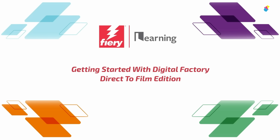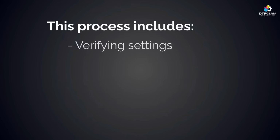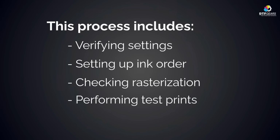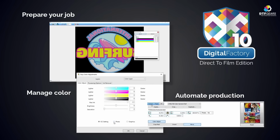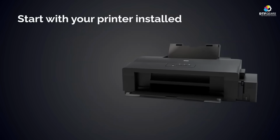Everyone! In this video, we'll cover the process of producing a DTF job using Digital Factory Direct-to-Film Edition. In this process, we'll cover verifying your settings, setting up your ink order, checking rasterization, performing a test print, and printing the job. Cadlink's Direct-to-Film Edition allows you to prepare your job, manage color, and automate your production with built-in tools. In this video, we are assuming you have your printer installed.